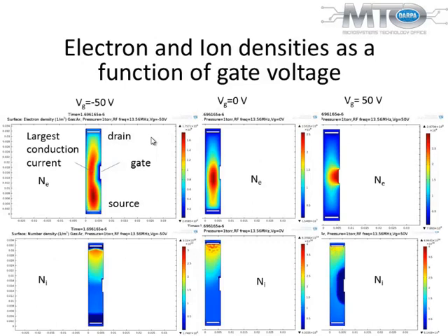I put this plot in order to show you that indeed you can simulate these things using COMSOL finite element and show that there is a gate field effect. The gate is right there. Let's call this drain and source. In these particular devices, the voltage applied between drain and source ionizes the gas inside this chamber, and the gate, depending on how much voltage you are applying, whether it is positive, 0, or negative, you can push away different species that you have inside the plasma.